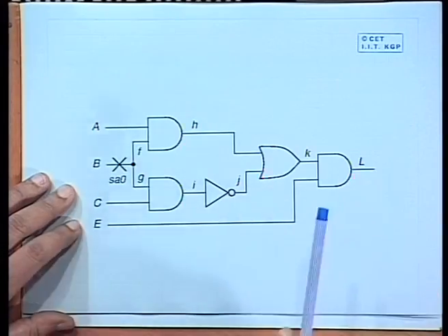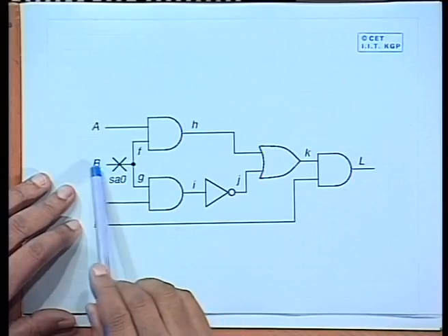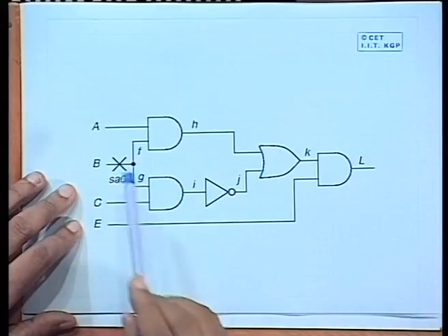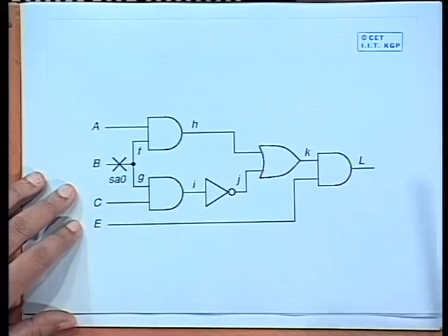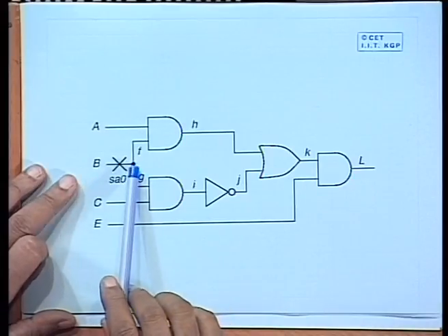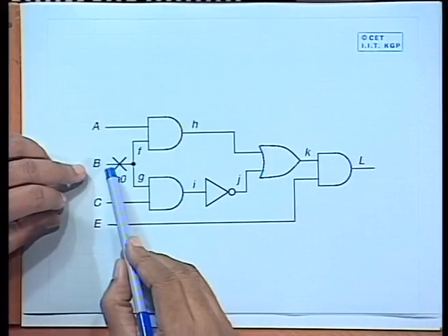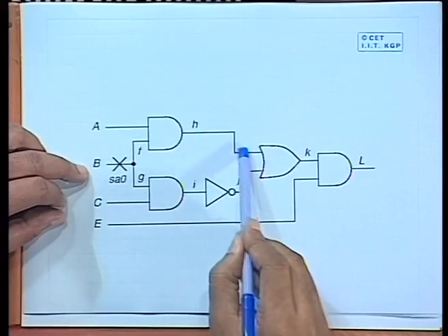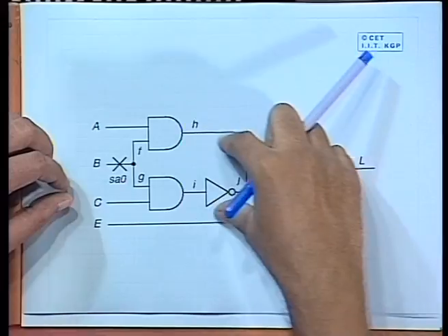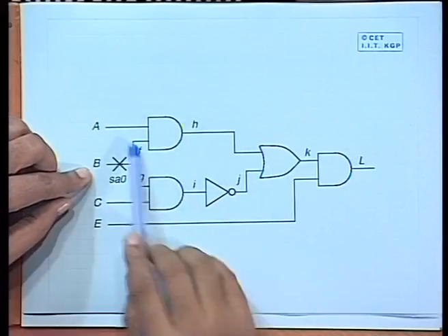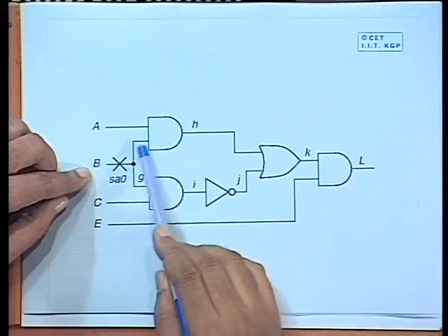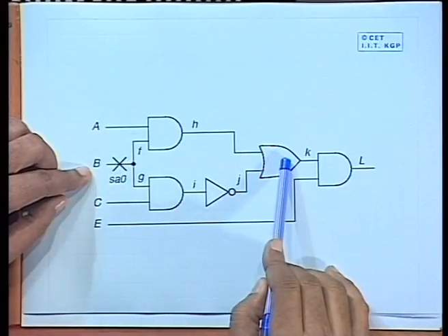Okay. So, let us take an example to illustrate how we do this. Let us take this example. This is a small yet somewhat complex example, because there are fan outs. Just to observe one thing, this circuit has a structure which, in terms of testing, is considered to be a complex structure. It has a fan out and also it has reconvergence, that means the fan out branches are finally merging into a gate down the line, in this OR gate. So, this is called reconvergent fan out.